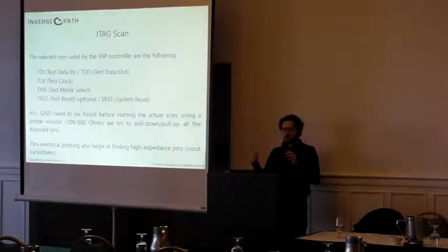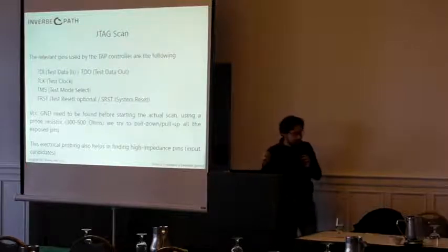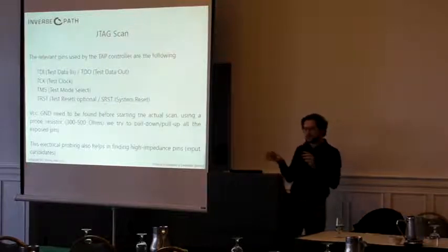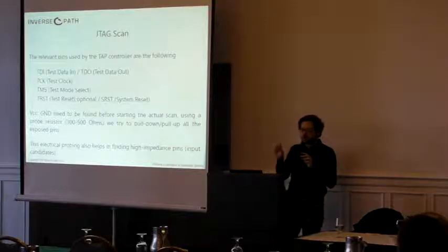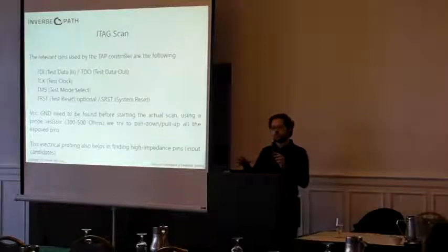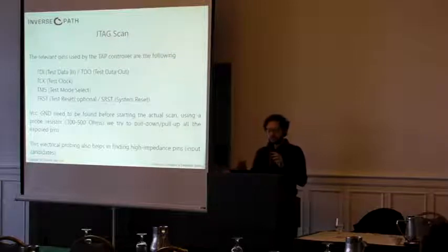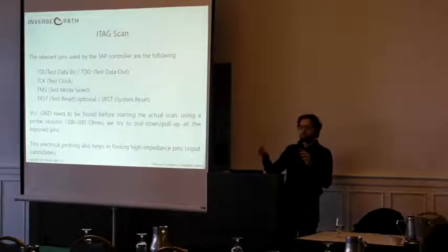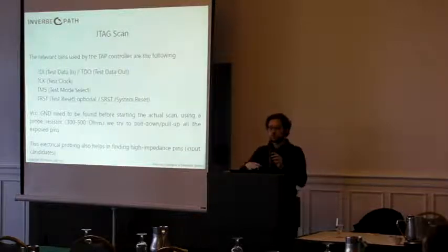in, data out, you have a clock, mode select, and then the reset pins, some vendors, or at least in many systems we found, they have two levels of protection. The first level of protection is that from an electrical perspective, things are not soldered and are not set up in a way that allows you to have JTAG access. So sometimes you have to remove a fuse, or you have to solder a bridge to add some resistor in order to have the circuit compliant to what you need to do.